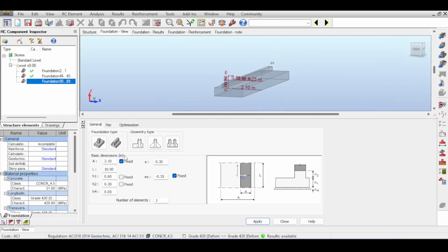All right, so our subscriber says that the base is actually 0.6 multiplied by the wall height, which should be 3.5 by 0.6, 2.1. And he distributes this into 2/3 and 1/3. So the distance here is 1.4 on one side, and 0.7 on the other side. So exactly as his suggestion. And there was a suggestion about the wall thickness, but I didn't incorporate that.